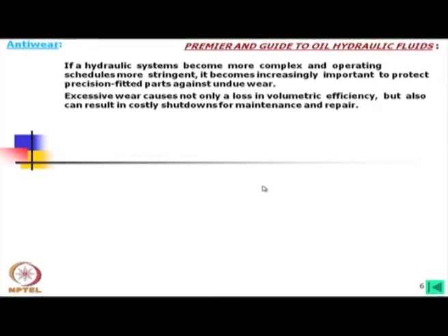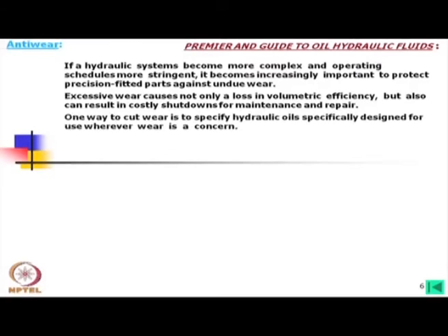Excessive wear causes not only a loss in volumetric efficiency, but also can result in costly shutdowns for maintenance and repair. One way to cut wear is to specify hydraulic oils specifically designed for use where wear is a concern.